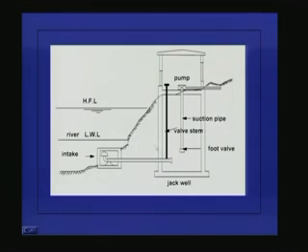In this case, here you have this intake structure. Now, this intake structure is placed much below the raw water level, so that water can enter into the well even during the low flow season. Here, this is the intake pipe, and there is a screen here which screens the debris from entering into the intake well or jack well, and we have a pump here which has a foot valve.